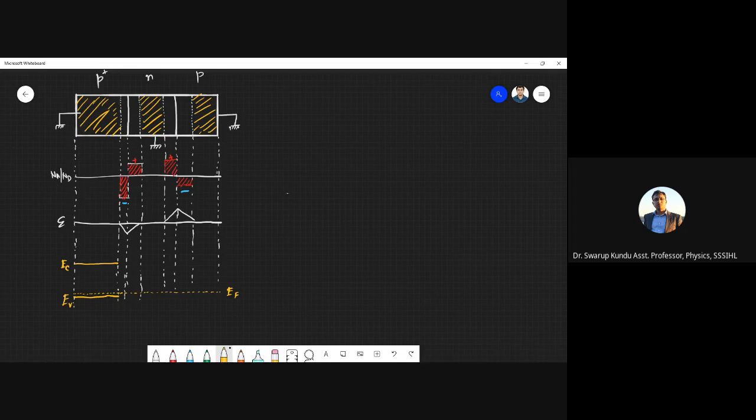Now, what about the N type? So we have to now draw the N region. So let's draw the N region. N region, okay. So for N region, the Fermi level, I mean the conduction band will be near Fermi level, right? So it should be somewhere here. Let's imagine. And so again, the band gap is same. Then you can do the same gap, right? This gap, do the EG. So this EG will be again same here also. This will be same, right?